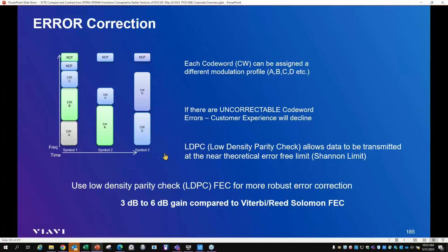Obviously the profiles are going to be different for that than for a carrier at 96 megahertz on the upstream, an OFDMA carrier, for example. But for downstream OFDM carriers, low density parity check has really increased the dynamics to deal with linear distortions, noise, et cetera, to maximize the capability of that OFDM downstream carrier.